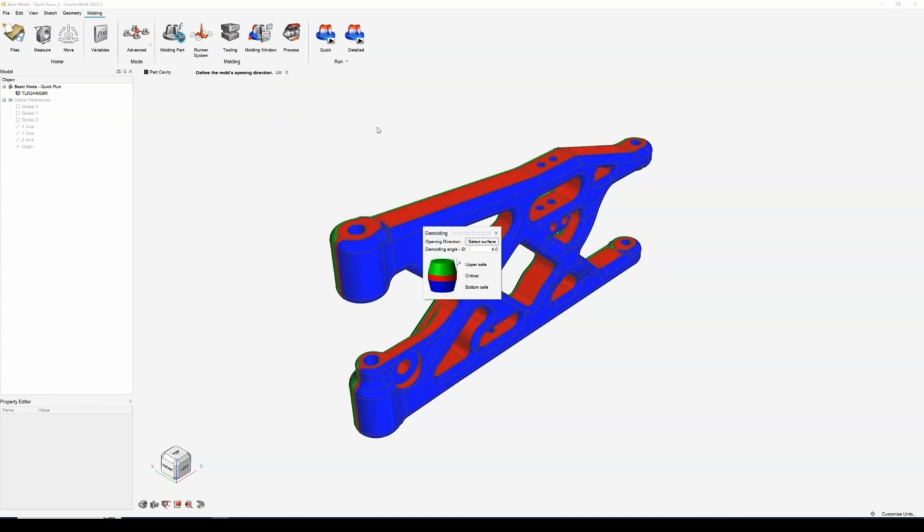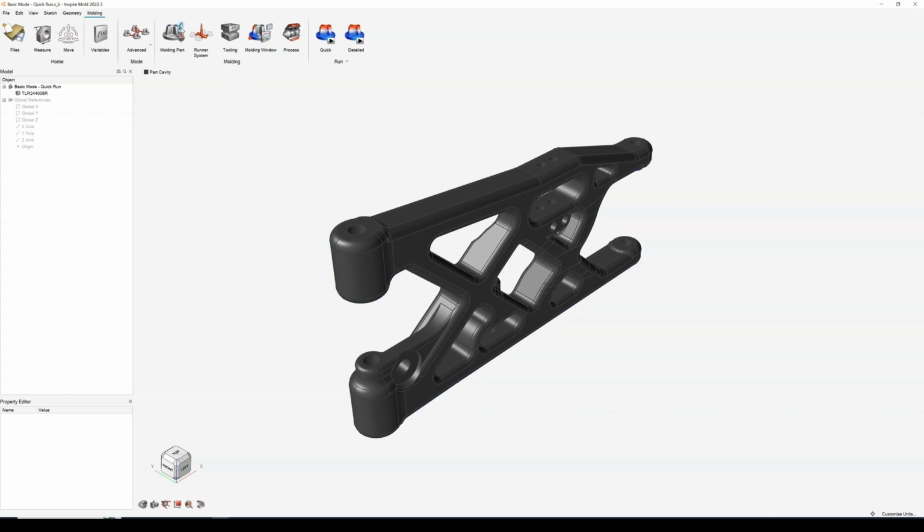It's exactly the same orientation as before, something we've already looked at. In here, we do have another tool, auto configure components. That is something I will quickly show at the end of this demo, after I've shown you the results, because it's quite a good tool. You basically import a whole mold. If you've got a whole mold with all your runner system and your multi-component system with your gates, your sprues, your runners, you can just specify an injection point in the software, and it intelligently defines all the different components. But obviously we haven't got any mold here, so I can't do that.